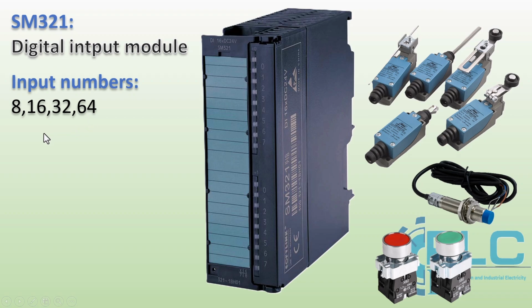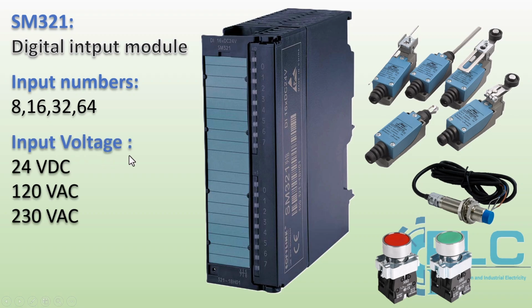Another important factor to consider is the input voltage rating of the digital module. This rating determines the voltage levels that can be connected to the module. Digital input modules are available in different voltage ranges, including 24-volt DC, the most common voltage used in industrial automation; 120-volt AC, often used in control systems where 120-volt AC signals are standard; 230-volt AC, typically found in high-power control applications. Before connecting input devices, it is essential to verify the module's voltage specifications to ensure compatibility with your system.